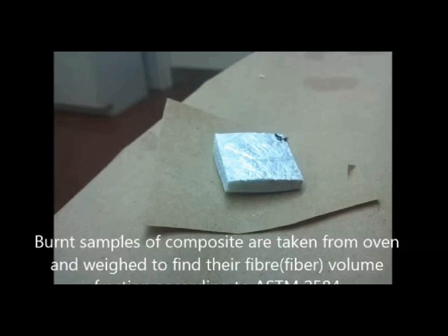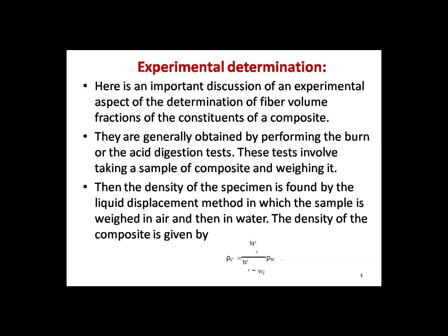So in this way, we can find out the fiber volume fraction with the help of the burn test, which has to be performed on a complete composite or on pieces of composite of dimensions 20 cross 20, and it also depends on the capacity of the oven. In the previous slides, we had demonstrated the carbon fiber extraction from the composite, and it will provide us the carbon fiber volume fraction.